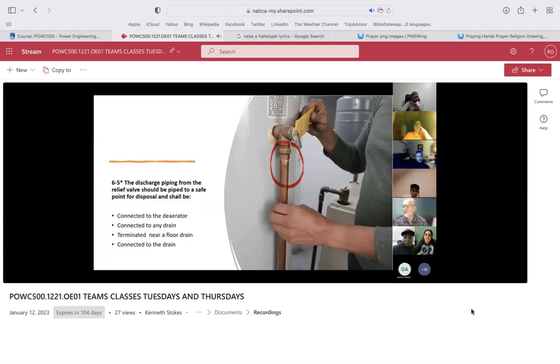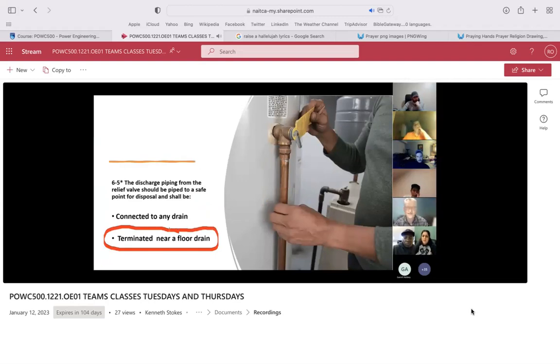Discharge from relief valve should be piped. So this is common now, they'll be connected. What happens at the other end of this pipe? Do we connect it to something or not? The sewer. Okay. It should be close to the sewer, but should have some airspace between the sewer and the drain, from what I read.